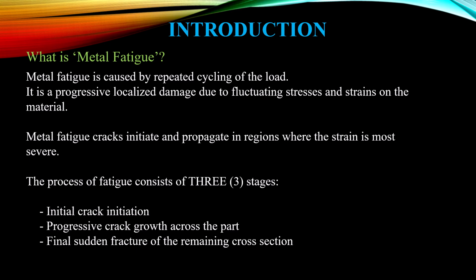So, what is metal fatigue? Metal fatigue is caused by repeated cycling of the load. It is a progressive localized damage due to fluctuating stresses and strains on the material. Metal fatigue cracks initiate and propagate in regions where the strain is most severe.